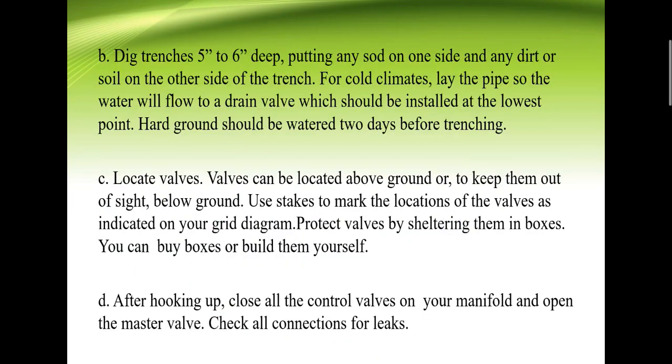B. Dig trenches 5 to 6 inches deep, putting any sod on one side and any dirt or soil on the other side of the trench. Just for cold climates, lay the pipe so the water will drain. Hard ground should be watered 2 days before trenching.